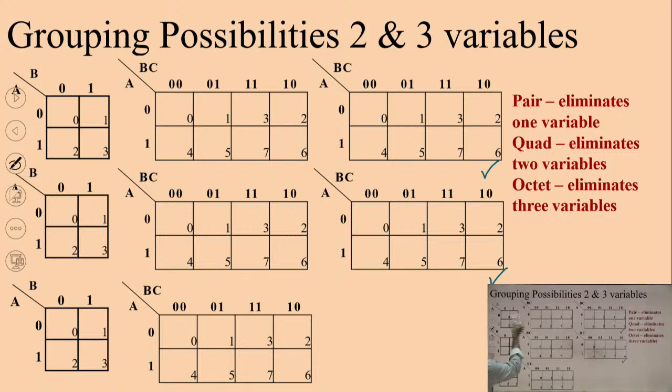Similarly, for this 2 variable K-map, now start practicing. If there are these 2 ones, there will be pairs. Sorry, these are not quads, these are pairs. Similarly, if these are the 2 ones, we can see that no pairing is possible. I am not even able to make two adjacent ones into one group. So these 2 will be singled out, which means this one and this one will be single ones. These are not pairs. Similarly, if all ones are there, then this will be a quad.